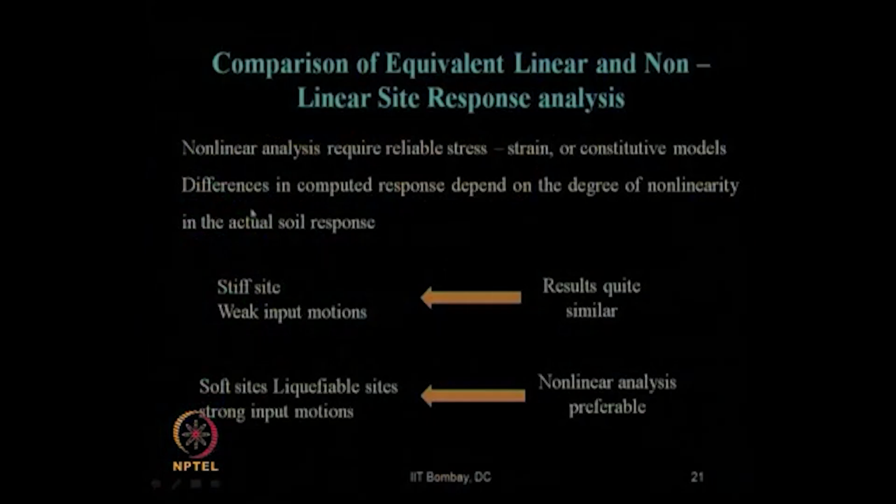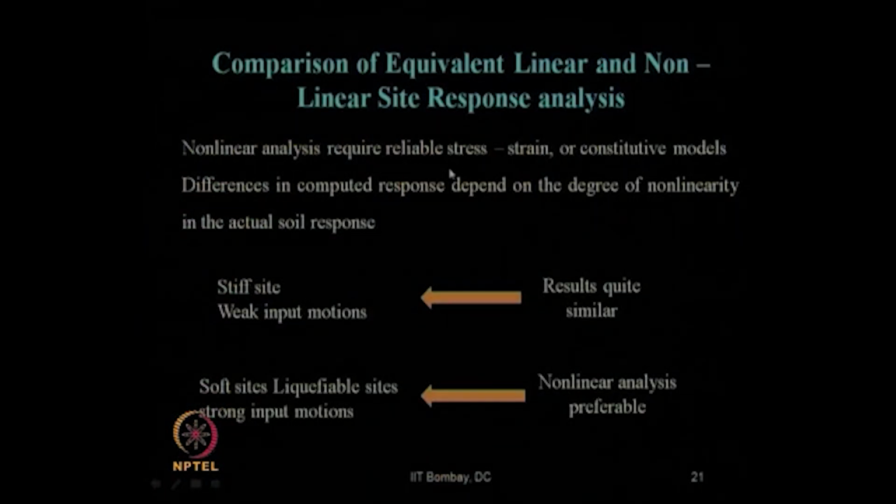Okay. Now, let us look at this comparison once further. Nonlinear analysis requires a reliable stress strain or constitutive model, which we have already seen. So, this is one complexity in the analysis. Differences in computed response depend on the degree of nonlinearity in the actual soil response. Suppose we are handling a stiff soil site, these are all relative terminology of course, with weak input earthquake motion, in that case nonlinear and equivalent linear will result in almost similar output.